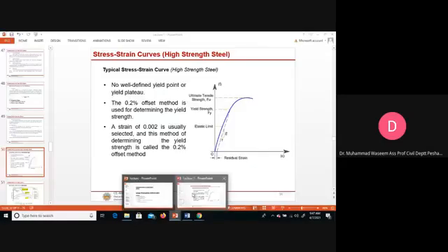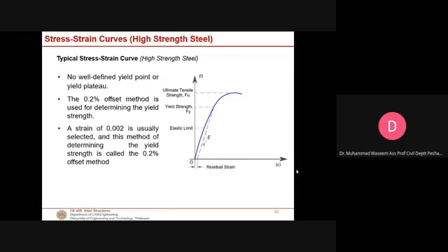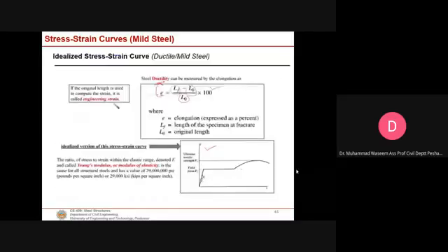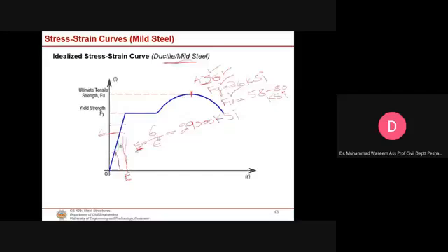Okay, there you go. Again, in the last session, we discussed the stress strain behavior of mild steel. We very easily could have looked at the yield strength and the ultimate strength by looking at the stress strain curve. If you remember, I'm talking about this stress strain curve. It's very simple. You can very easily pick the Fy, and visually it is possible for you to look for the ultimate strength of this material.